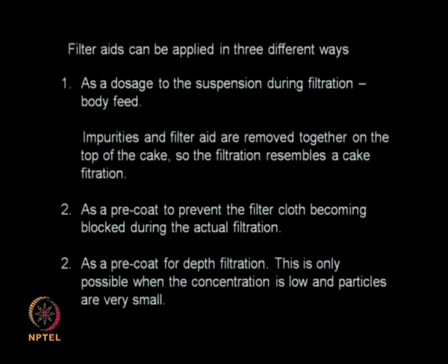So you need to consider all these aspects before deciding on the type of filter aid you would like to select as well as the particle size of the filter aid. These filter aids can be applied in different ways. I can add this filter aid as a dosage to the suspension during the filtration process. What happens is the solids settling on top of my filtration unit and the filter aid settle, so they can be removed together. It is like a filtration process where I have the cake as well as the filter aid retarding the flow of the liquid.